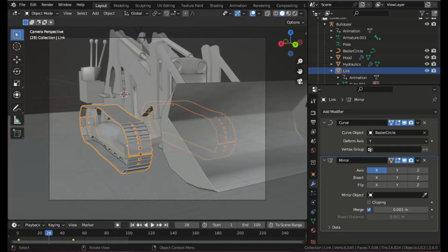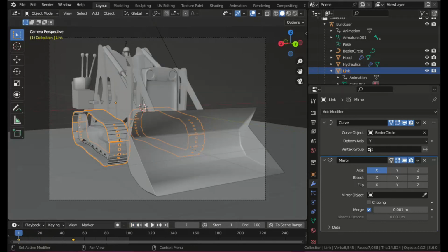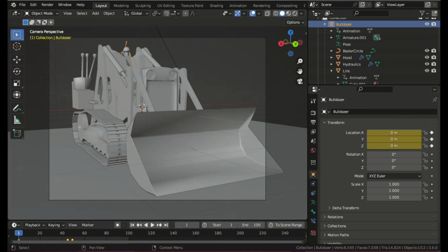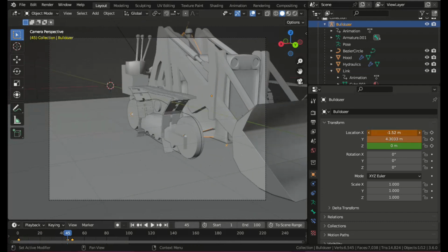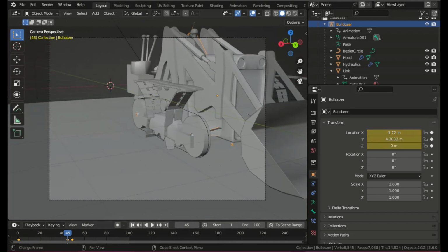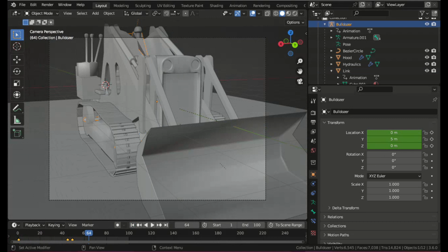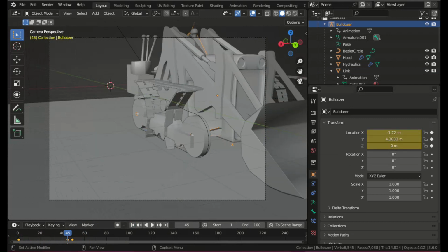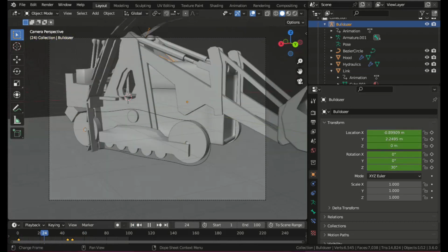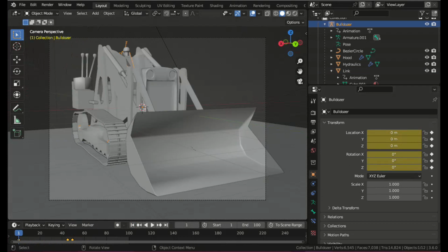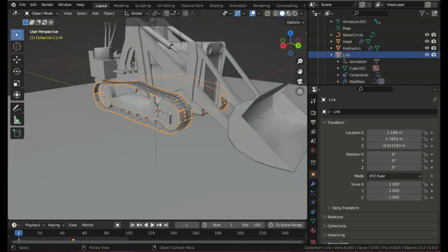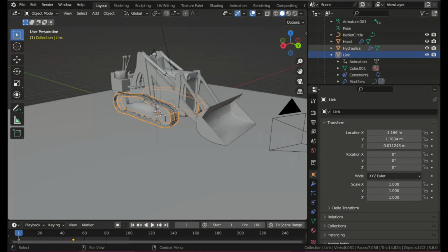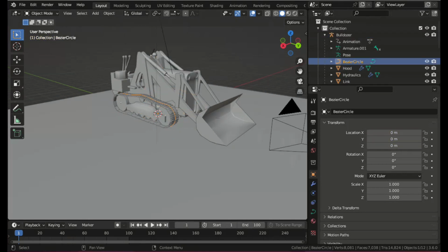Start with the model bulldozer in the link below that's on the Get Into Blender webpage. And we'll see that although the animation works fine when the bulldozer moves along the y-axis, as soon as there's any sideways movement or rotation or vertical movement, the modifiers to make the track run along the curve just stop working. And the reason for this is that the curve modifier and the follow path constraint both require world coordinates.